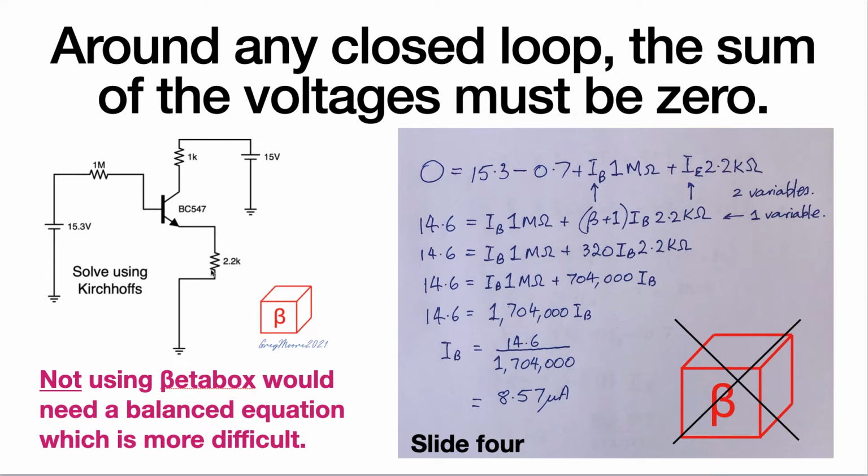You might recall from basic transistor theory that IE is equal to IC. This is because the alpha of the transistor, which is the ratio between IC and IE, is usually about 0.99. So some years ago, most textbooks decided that they were as good as equal, so IE equals IC.